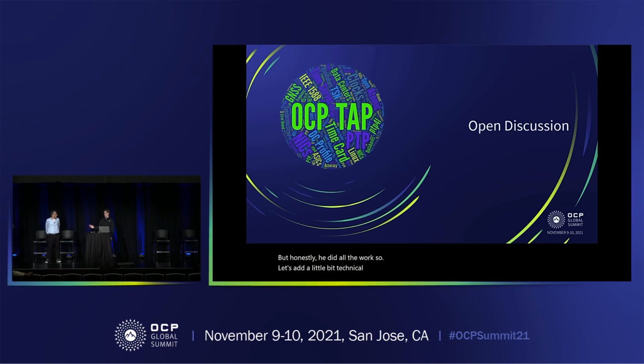Yeah, so I'd agree with Alad's point there. If you have a commercial off-the-shelf Grandmaster, basically it's not your problem, it's their problem. But once you put it into an open time server, you own the hardware, you own the NIC, you own the software. Any kind of deployment issues such as needing the 24-hour holdover is a big requirement. So that's a pretty unique requirement from other Grandmasters. We have to make sure the hardware is up to spec. We have to make sure we're using a good oscillator that we can source, that is reliable and meets all of our requirements. Those kind of challenges were different than an off-the-shelf server or off-the-shelf commercial Grandmaster.